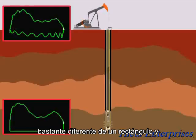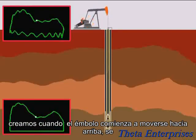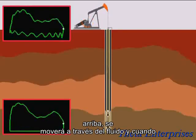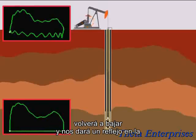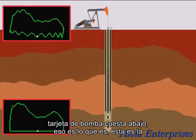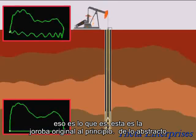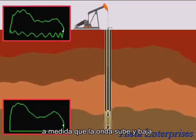That causes the dynamometer card shape to be quite different from a rectangle. Also, the wave that we create when the plunger starts to move up will move through the fluid, and when it reaches the surface, it'll bounce off and come back down, and it will give us a reflection on the downhole pump card. This is the original hump at the beginning of the upstroke, and this is the reflection of that as the wave moves up and comes back down.